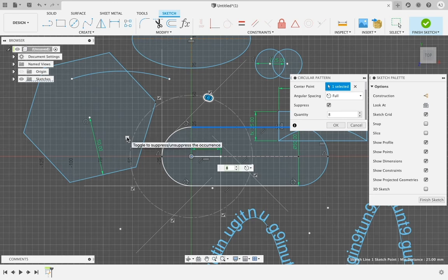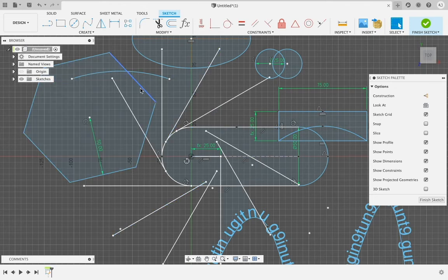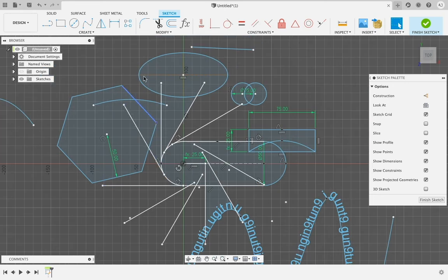Next, we can select these points here, these check markers, if we want them to actually show. Well, maybe if we don't want one there, if we want to leave some space, this is very useful, using the suppress tool. As you will see, it is now 11 blades, considering that we removed one in the process.